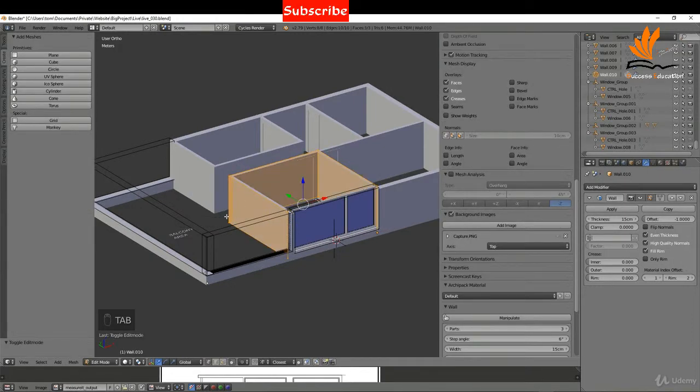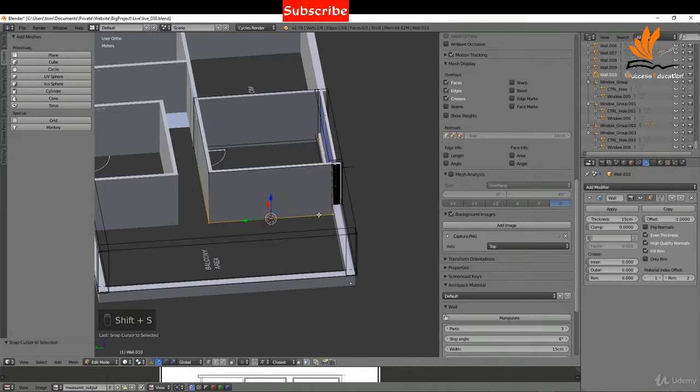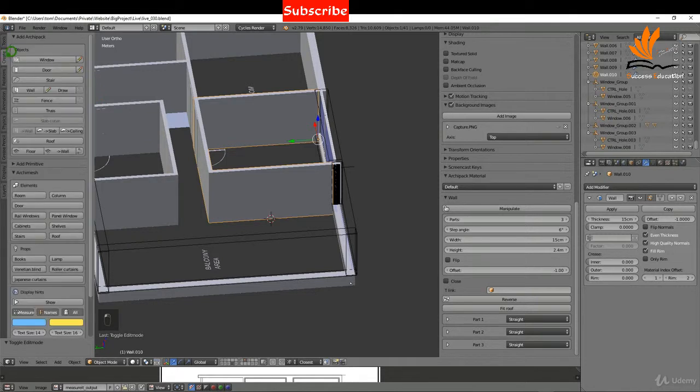So I'm going to tab into edit mode. Just going to select an insertion point with these 2 verts here. Shift S, cursor to selected. And I'm going to come back to object mode. So if I come up to create, and if I come down to Archimesh, I'm going to choose panel window.